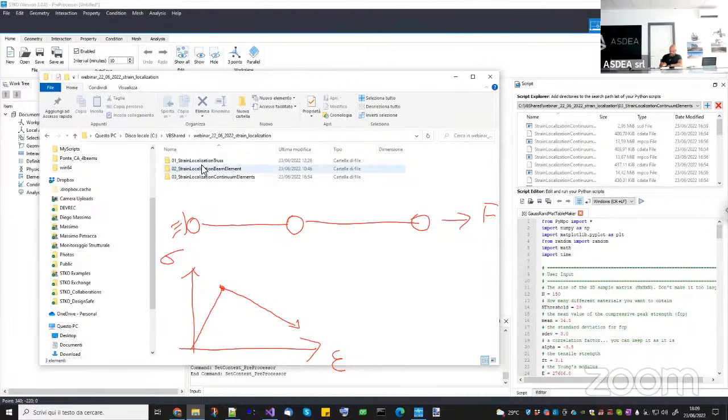So what happens is that when one of them reaches the peak strength, like this one, now imagine one of them is slightly weaker than the other, because in reality, the distribution of strength parameters and stiffness parameters are not exactly the same, so there are imperfections. So one of them will be weaker than the other. So this one will go in the softening regime. Okay, so this one is the path followed by element 1. This one is element 1, and this one is element 2. Now, since they are connected in series, for equilibrium, the other elements should have the same stress.